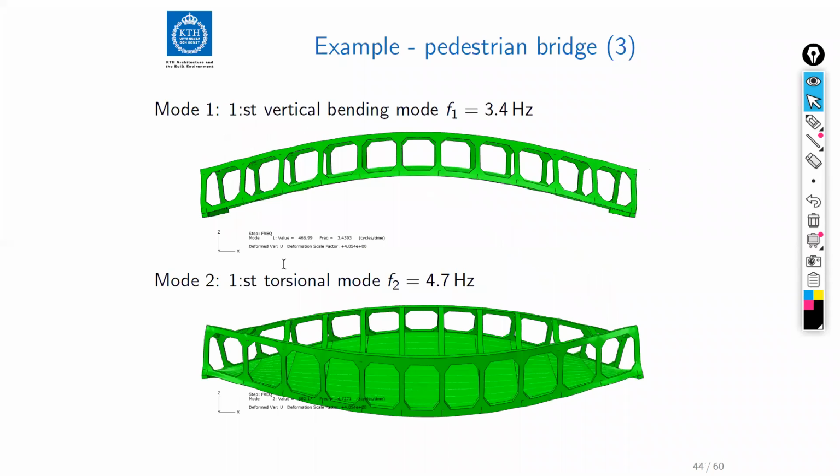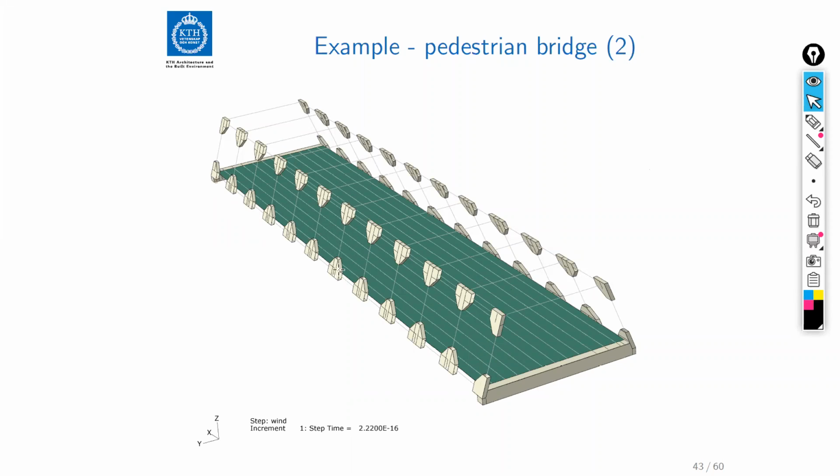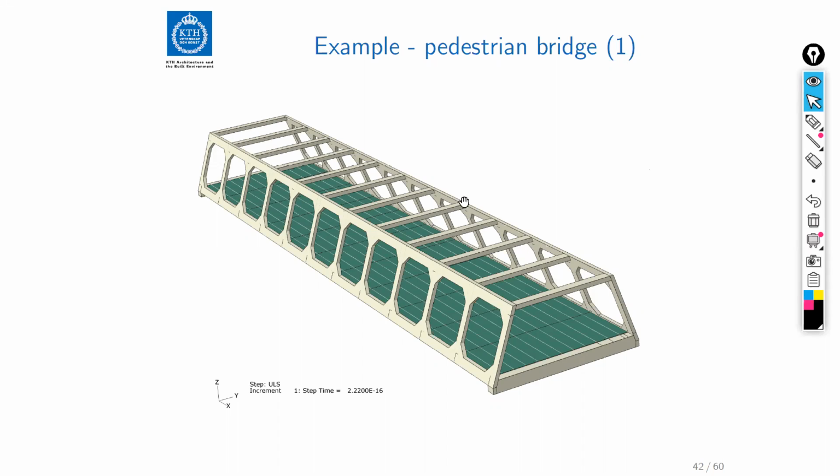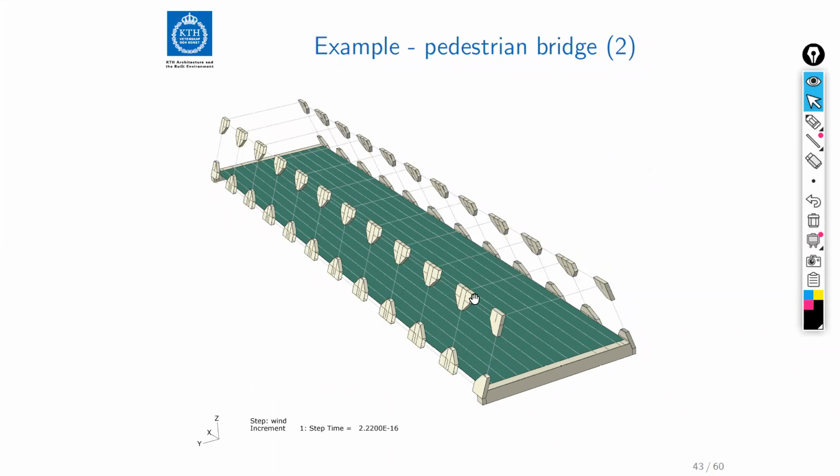So they wanted to make a simplified model, and they did some combination of a beam model and a shell model, because they realized that this is very difficult to model using beam theory. I'm not sure if it's doable really. They used shell elements to define the deck, but they wanted to model the top part of the superstructure using beam elements. These are all welded beams.